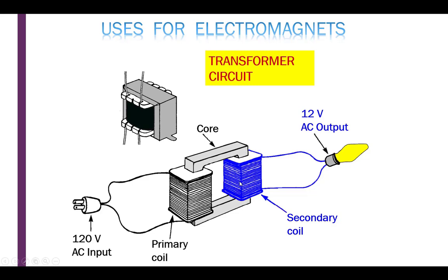The coil's stationary. It's not like when I was holding a conductor and running it through lines of flux. Here, the coil is stationary and the lines of flux are moving, but that motion is enough to induce a voltage here.